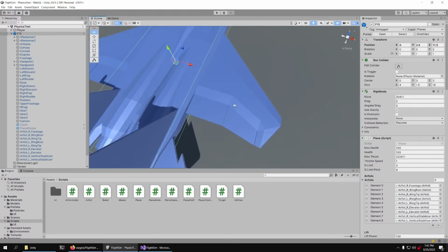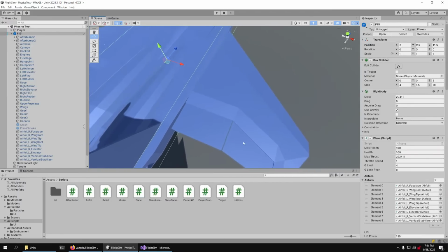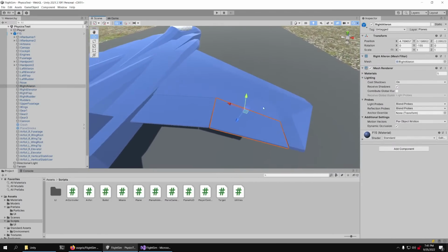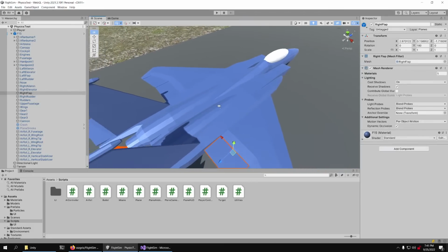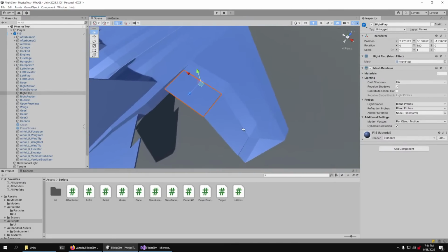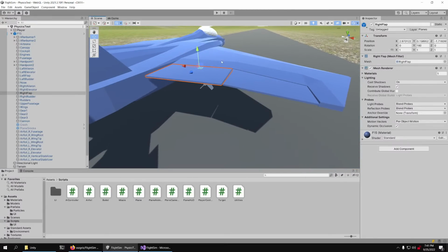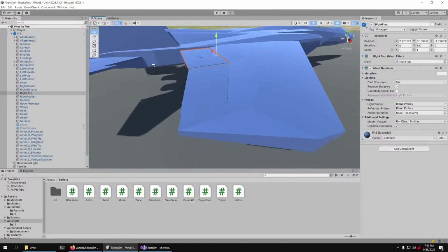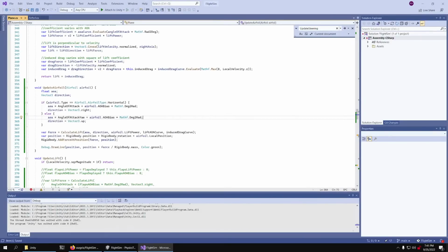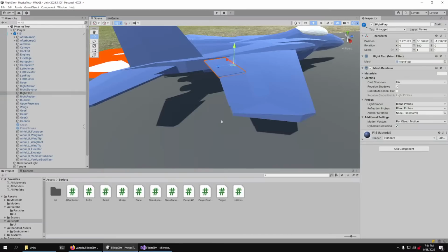So one thing I want to add here is changing this flap. Right now we can control the aileron, which is used for rolling. We don't have a way to control the flap, which is used for generating more lift during takeoff and landing. And it actually functions the same way as an aileron, which is to say that when the flap goes down, it just generates more lift for this segment of the wing, but it's not controlled by the player's control input variable. It's actually controlled by this variable here, flaps deployed, which is just a separate control that only works at low speed.